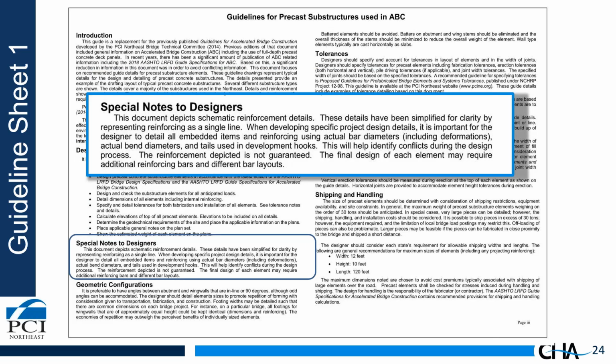We include special notes to the designers, and the note here is noting that the details included are schematic. They are not exact. You can't just copy them, put them in a project, and put it on the street. You actually have to design connections and design the reinforcing in the elements. That is all covered in the guide specification for ABC, but we had to make sure we make it clear. You still have to design the bridge and the connections.